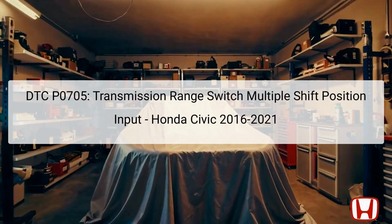The Diagnostic Trouble Code, DTC P0705, pertains to the transmission range switch multiple shift position input, specifically related to the Honda Civic models from 2016 to 2021. This code indicates a problem with the transmission range switch, which is crucial for informing the vehicle's onboard computer about the position of the shift lever.